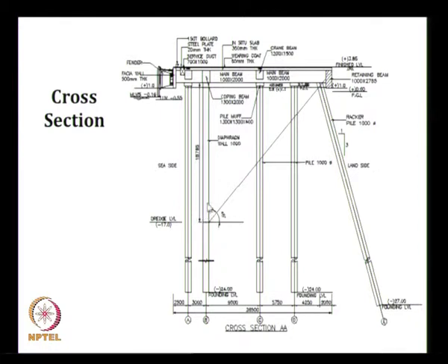That is why we are providing the diaphragm wall here, and we have a crane beam here, another crane beam here, and this 45-degree line is called the active edge. If your pile is in the active edge, it will not resist any lateral force. If you are modeling springs, you have to model the spring below this level, similarly for this level, and we provide a retaining beam at the end. This will be designed for the surcharge pressure, so that we transfer the lateral load here.